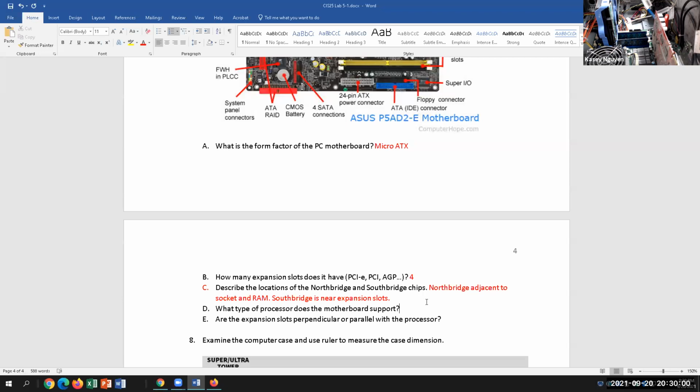What do you think about the liquid metal? Yeah, liquid metal is good too. So when you put it on your processor, I normally take a piece of cardboard and scrape it so it doesn't drip, or you just need maybe the tip of your pinky. You don't need too much. Don't make it ooze all over your motherboard, or it'll ruin your motherboard. So you just need a little bit, scrape it even, then put your heat sink on top and put it all back. They dry up every so often, so you should replace your thermal paste every few years. Okay, so I would say this is Intel vPro inside.